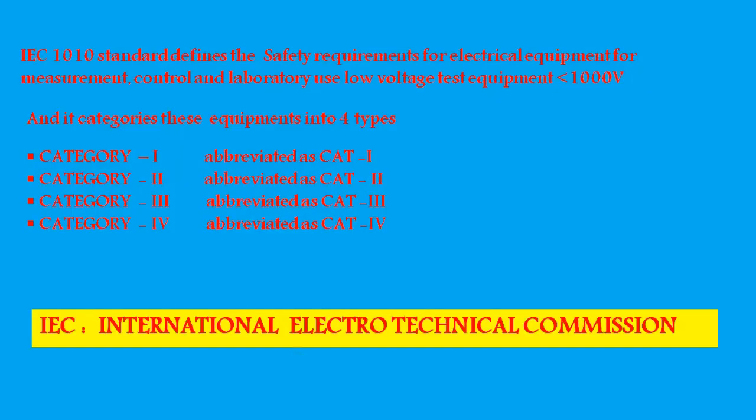CAT rating is called category rating, and these ratings are standardized by IEC, that is International Electrotechnical Commission. This IEC defined a standard, IEC 1010, which talks about safety requirements of the equipment that is being used for measurement, control and laboratory use in a supply less than 1000 volt. This standard divides multimeter into four categories.